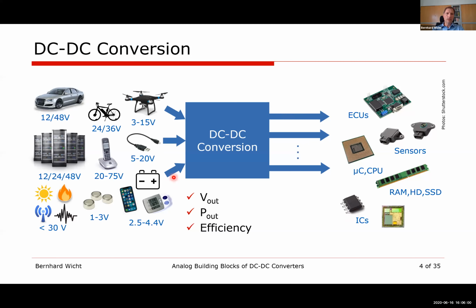DC-DC converters are the key element in the growing area of power management, and they simply link the voltages that occur at the application level from various energy sources with various voltage levels to IC level voltages that we see here on the right.